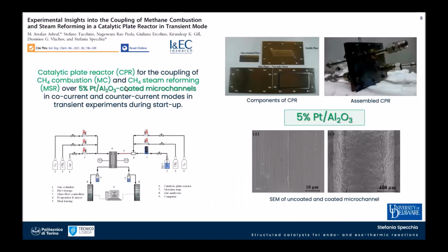From this point of view, a couple of years ago, we had a cooperation with the University of Delaware for the concept of the integrated microreactor, by coupling the reforming reaction, which is an endothermic reaction, with a combustion reaction in order to directly provide the heat of reaction to the system. So we were using this kind of metallic plates. The concept is, as I was mentioning before, the concept of a plate heat exchanger, where on one metallic plate we have channels on both sides.